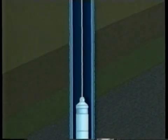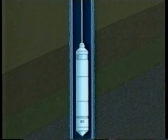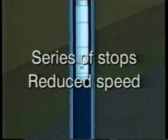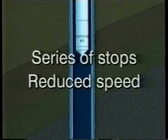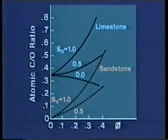2 logging speeds are necessary due to the shallow depth of investigation and the low count rates associated with certain elements. Therefore, the tool must be run once at speed, and then again at either a series of stationary sampling stops or a reduced speed. The measured carbon-oxygen ratio varies as a function of porosity, lithology, and oil saturation.